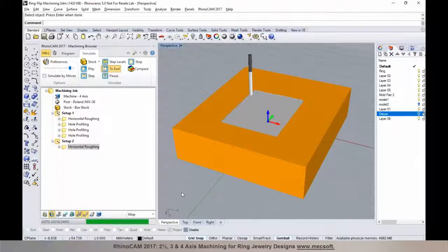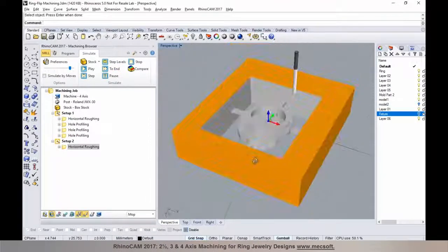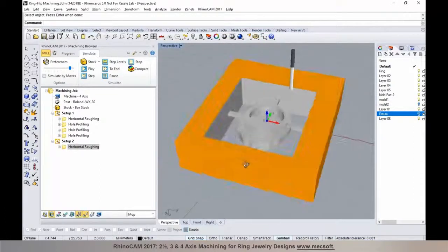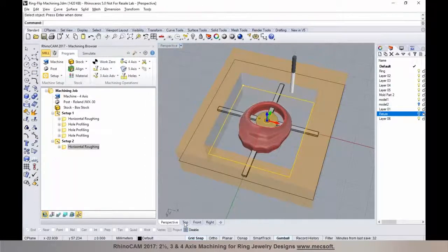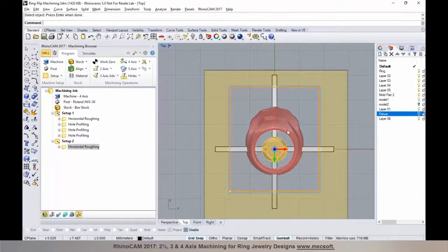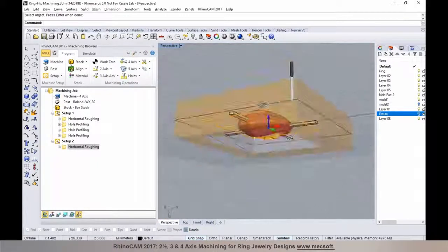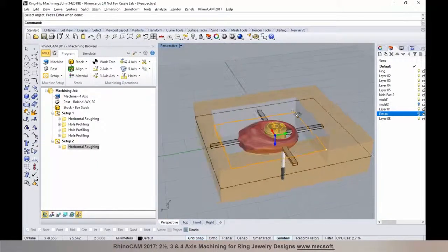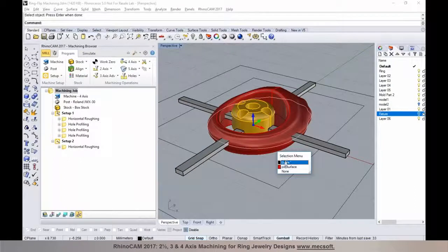So once the roughing operation is completed for both the sides, now it's been completed for the 2 sides, we would want to go back and add some finishing operations. So I'm going to switch back to the Program tab in here. And the most commonly used type of finishing method in here would be a radial machining operation. So I'm going to define a couple of boundaries in here. So I have 2 boundaries that are right on the edge of the part.